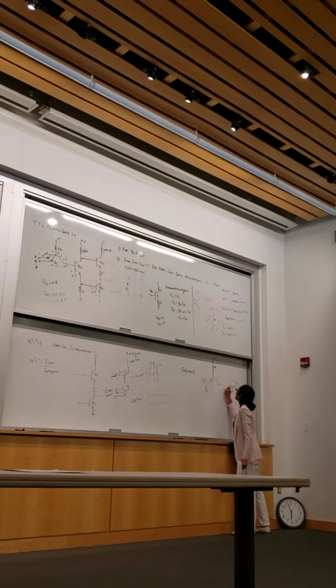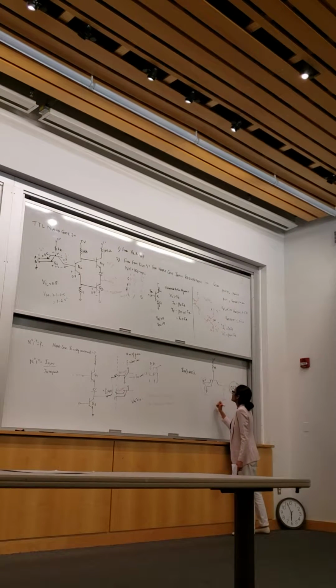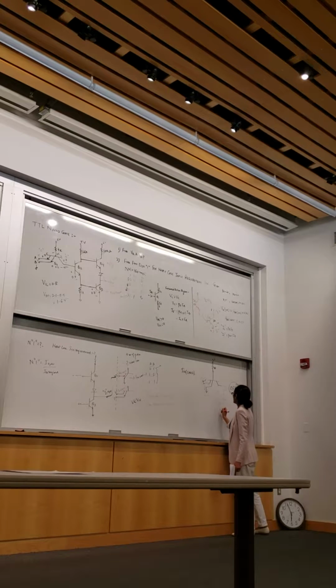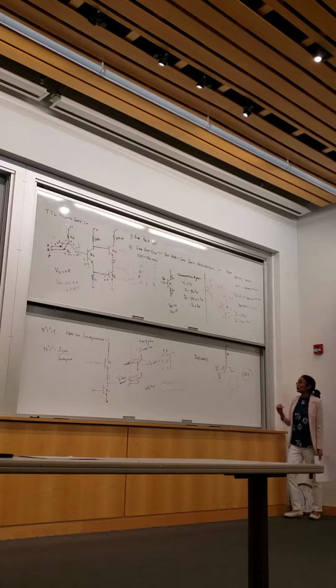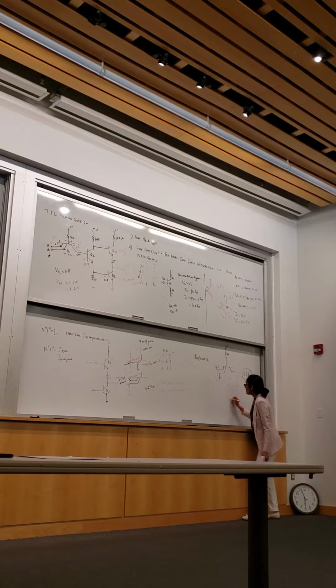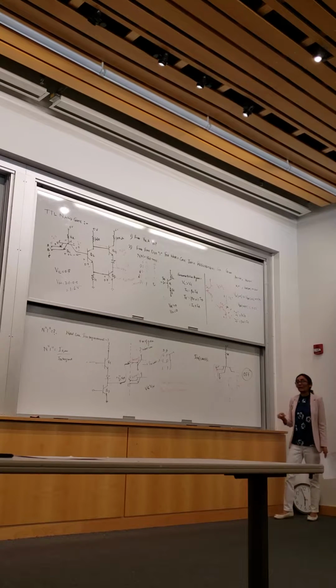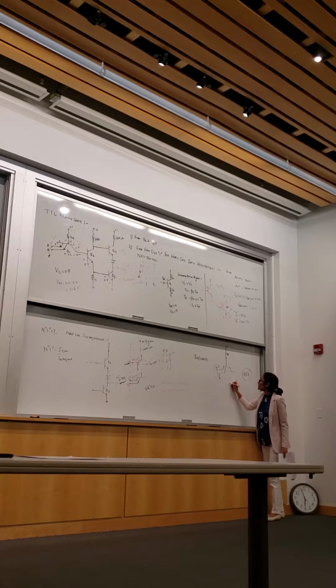This is 4K and that's 5 volts. This is 5 volts. This is grounded. So this node is at higher potential than this one. Whichever node is at higher potential, the current in that branch will be related to IB through beta L, as beta L IB1. And the current here, although we are not interested in this, is beta L plus 1 IB1.